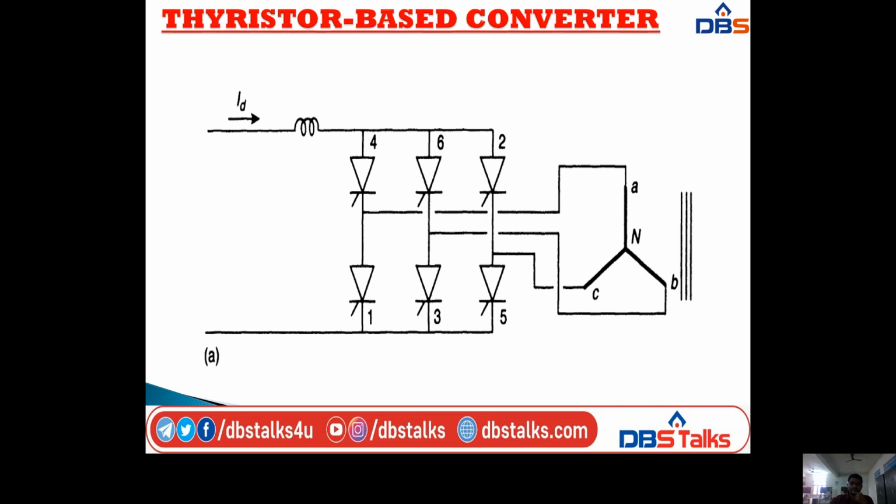This is the diagram I am discussing. On the left side we have the thyristor connections. Here we are using 6 thyristors, and next we have the inductor for the DC side. On the AC side we have the 3-phase connection, consisting of 3 terminals A, B and C, and a neutral connection also, that is N.